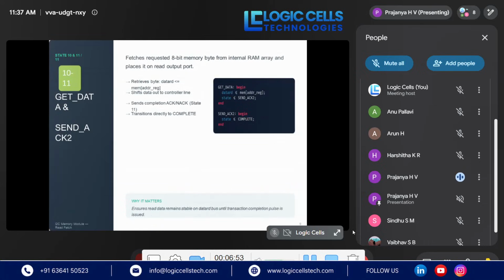The next state is get data and send acknowledgement. The FSM retrieves the 8-bit data from the selected memory location and places it on the appropriate data register output. And in send acknowledgement, after receiving the acknowledgement, the controller indicates that the read data operation has been handled.